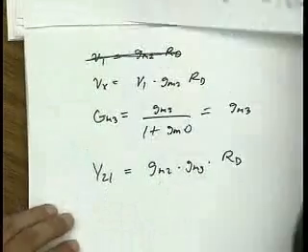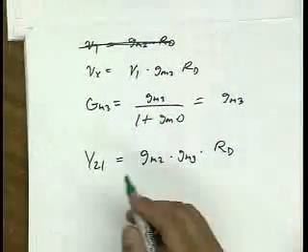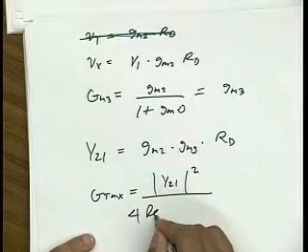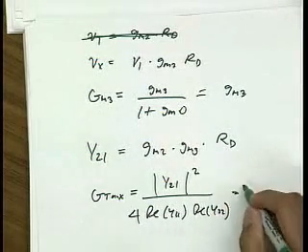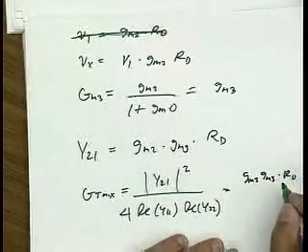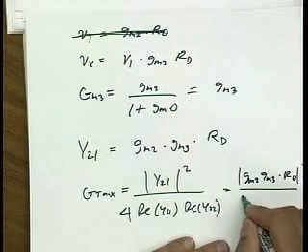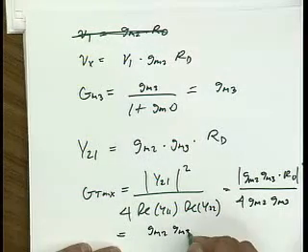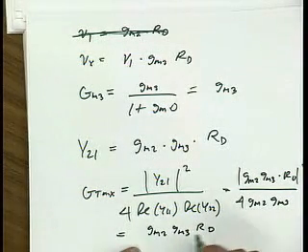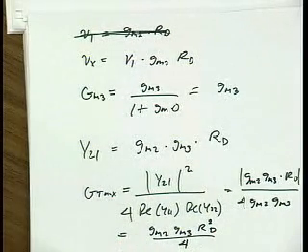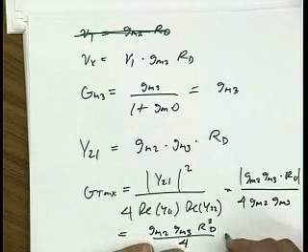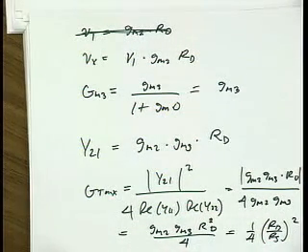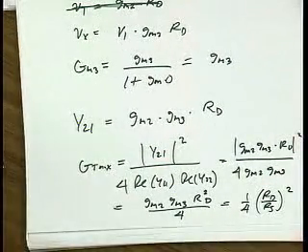All right, good. Okay, so now I have all the Y parameters, and based on the formula, GT max, it's stable because it's unilateral, so I can just use this equation. So this gives me GM2, GM3, R drain squared divided by 4 GM2, GM3, or basically R drain squared divided by 4. Okay? And if we assume that this is actually matched so that the GMs are equal to the source impedance, I get 1/4 R drain over RS squared. Okay, any questions?